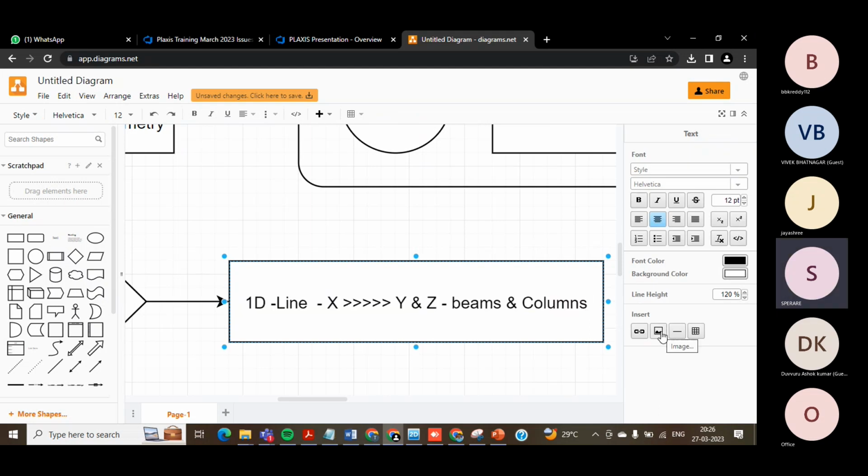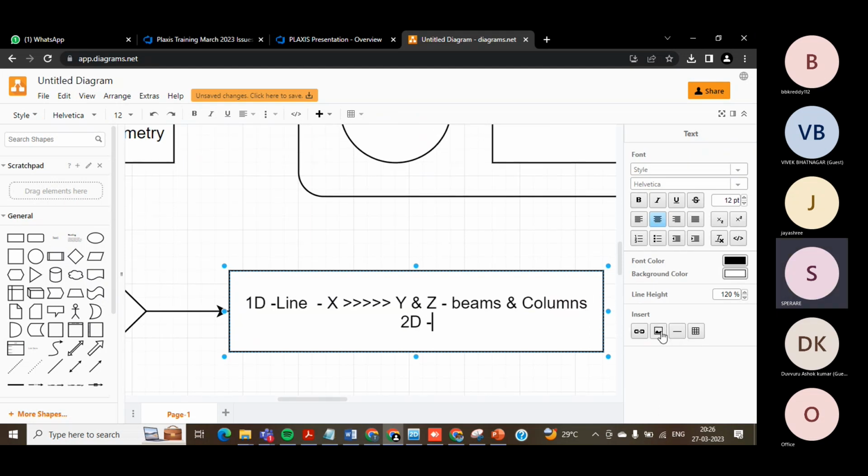And you consider it as 2D when X and Y are too greater than Z, or the other condition is X and Y are too less than Z. If I have some 2 to 3 kilometers of embankment, where I would be considering only a plane of that particular embankment, that is where I can consider it as 2D.